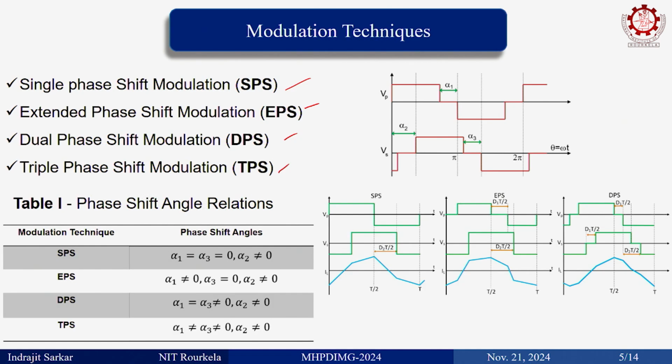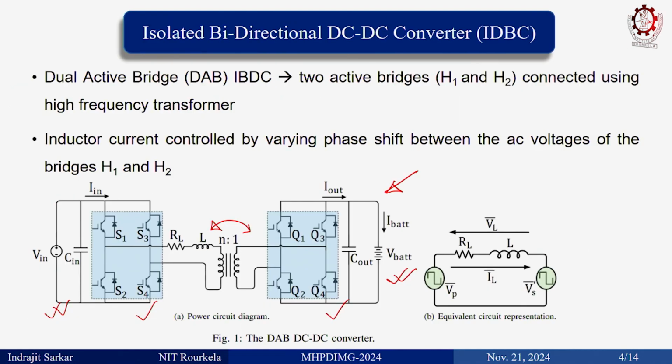Here we have a battery. Battery charging can be done using two methods, CC and CV: constant current charging and constant voltage charging. Constant current charging means irrespective of battery voltage, you are pushing a constant current to the battery. For DC fast charging, it is almost 1.2 C or 1 C, something like that.